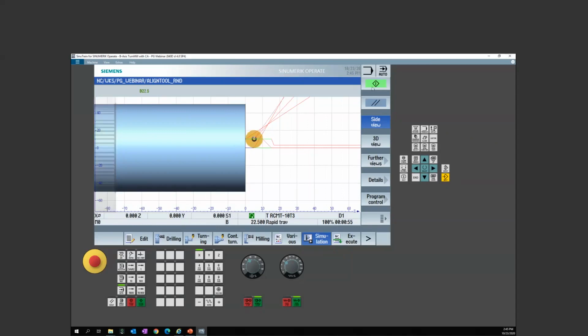If I stay within that 45, that 22.5 degrees, so half of 45 on either side, it will stay in cutting edge position 3. But once I go beyond it, so I went from 67.5 to 68 degrees, it's now going to shift off, and I'm now overcutting or undercutting because I wasn't anticipating that.